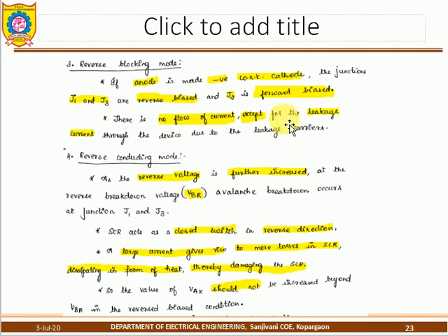Then, as you keep on increasing the voltage, the reverse breakdown takes place. Once the reverse breakdown takes place, the switch is closed, so current flows in the reverse direction. Due to that reverse flow, heat is dissipated. A large amount of heat is produced due to the high loss in the SCR. Due to that heat, the SCR life is reduced and it gets quickly damaged.